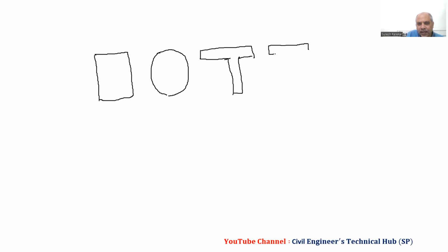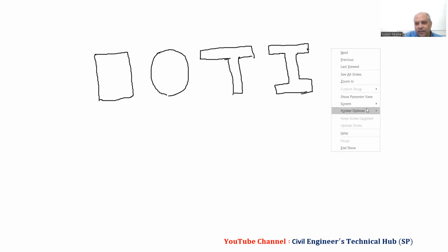Your bending stress diagram will not change its shape. For all these, my bending stress diagram is the same, and therefore you should not confuse bending stress and shear stress. Bending stress diagram is always linear.